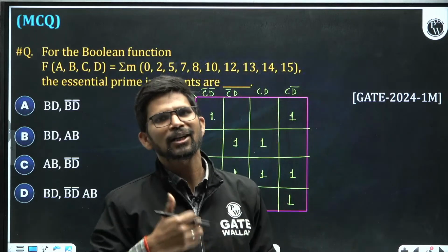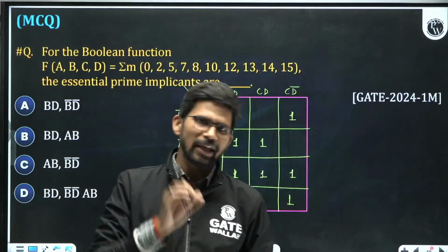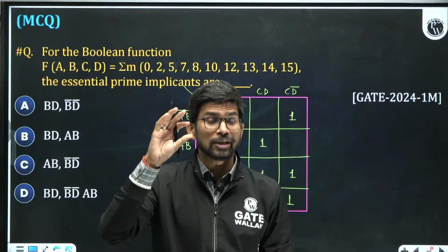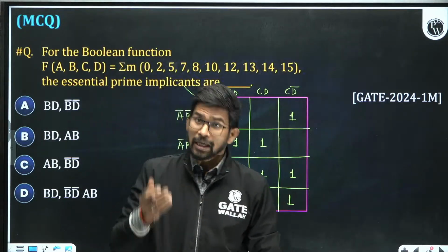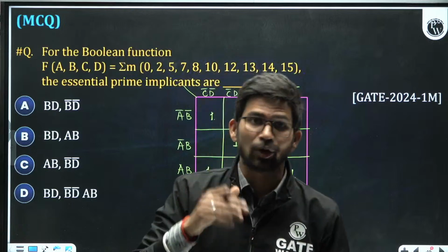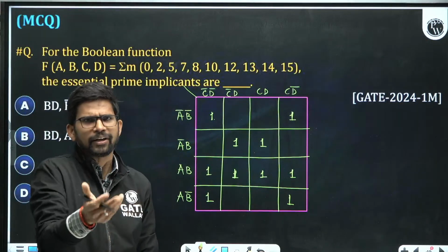So finding out the number of prime implicants is the most important task. And in that, firstly try to form the best possible groups as you do in solving a K-map question. Then by using overlapped ones, if you can form a group which cannot be combined further, that will also be a prime implicant, which will definitely be a redundant prime implicant.